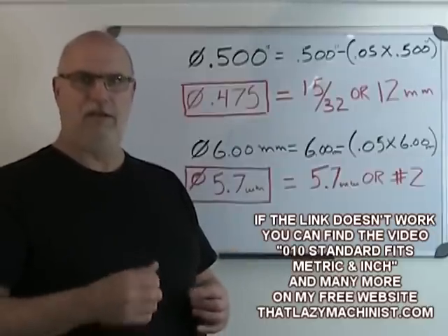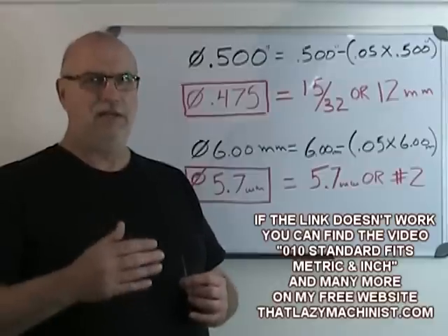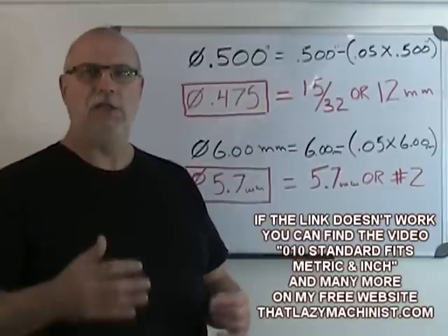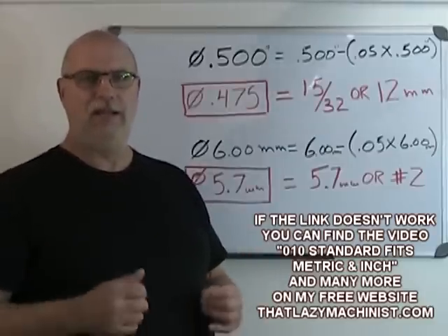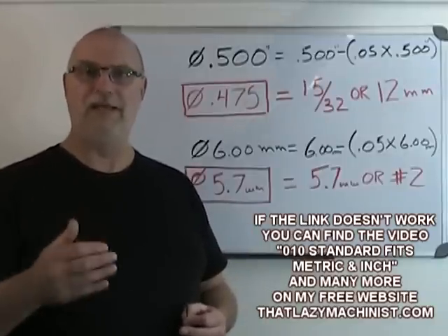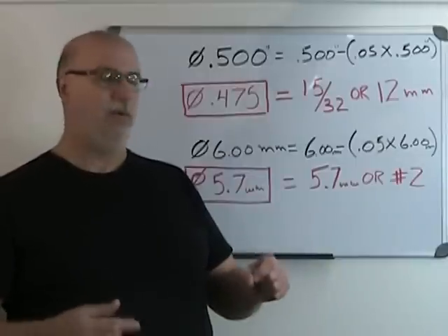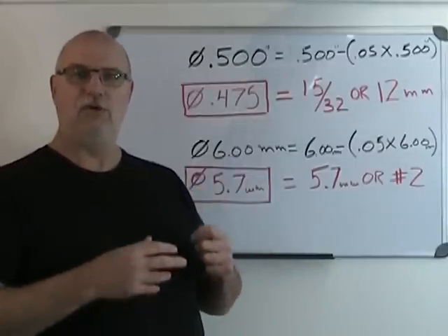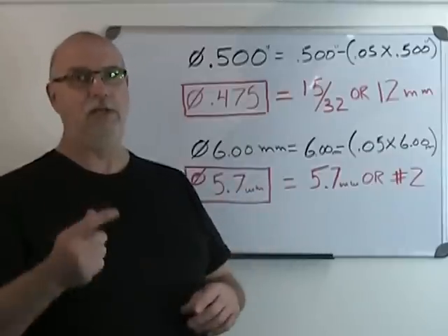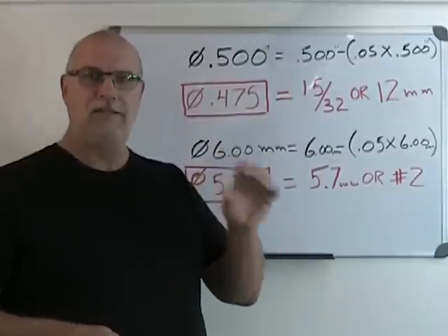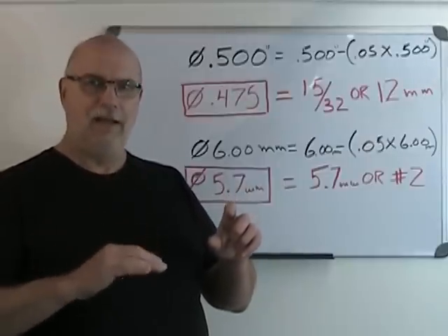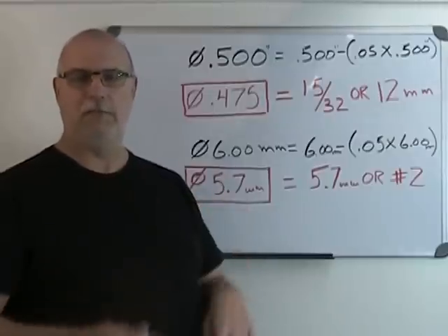And that's one reason that would make reamers interesting, because that preferred dimension applied with the second reason, which would be hole-based systems. It's much more difficult to produce an odd-sized hole than it is to produce an odd-sized shaft. And that is why when we design, we usually apply hole-based systems. And that means that if I have a hole into which a shaft must be inserted, well, I'm going to design it so that the hole is the base dimension, the preferred dimension. So let's say it was a 1-inch assembly, 1-inch hole, 1-inch shaft, and I wanted a little clearance. Well, I'd make the hole exactly 1 inch, or very slightly larger, but not smaller, and I'd make the shaft 1 inch a little smaller. Okay, I make the shaft slightly undersized to get my fit.